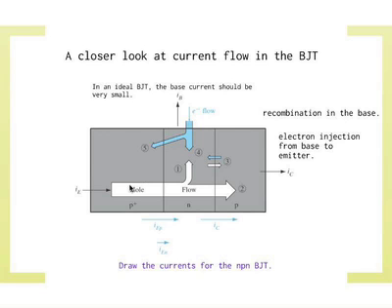So to understand that, of course, it's very straightforward because this is a forward bias p-n junction. When you have a forward bias p-n junction, you have majority carrier injection. The energy barrier here is lowered, and the electrons get injected across. Holes get injected across from the p plus to the n-type. And if those holes can make it across the base, then it can form part of the collector current. That's the idea. You make the base very small such that the holes will basically diffuse across without being lost by recombination. So that's the main thing to understand.